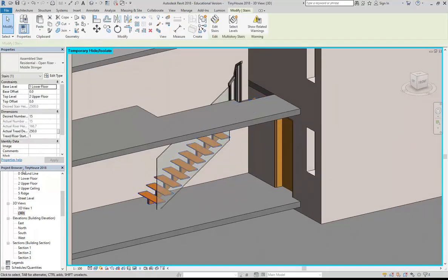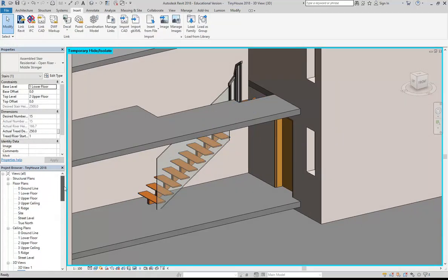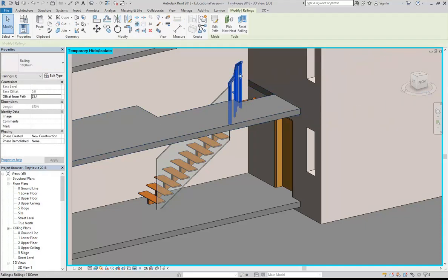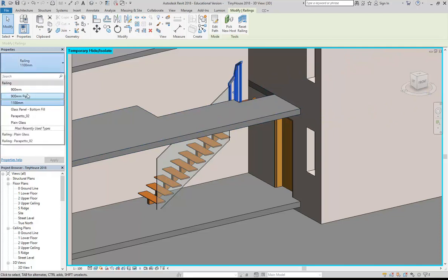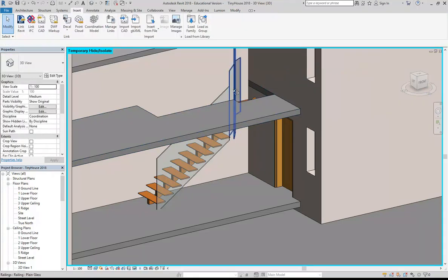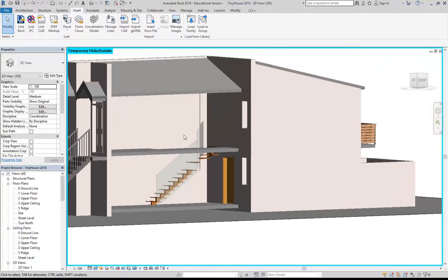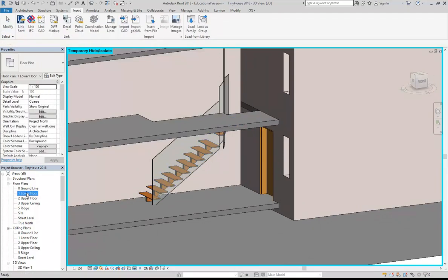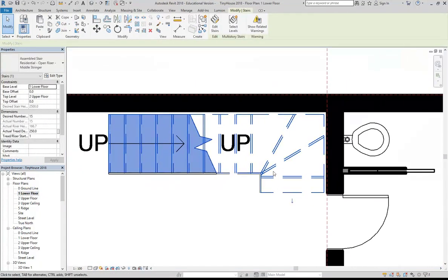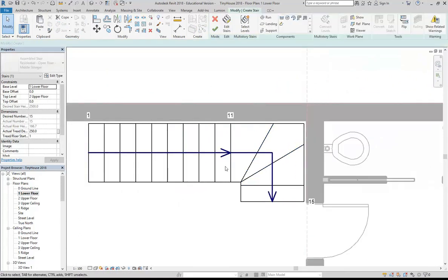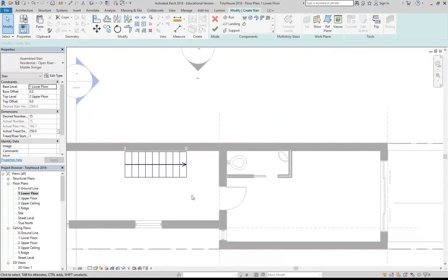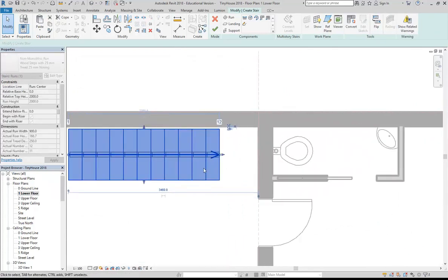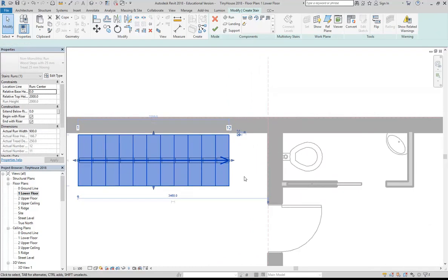There's nothing you can do really about that. So, yeah, but the winder though should... Around here? Yeah. Oh yeah, of course, yeah. And so this one as well, I can just set to my plain glass. And then you can see again where you'll have some issues because of the heights and things misbehaving. So it's all because of that winder. Winders are okay, but they sometimes take a bit of working out. So I go to Edit the Stairs and delete all of that, and then I'll just extend this to have a couple more steps.